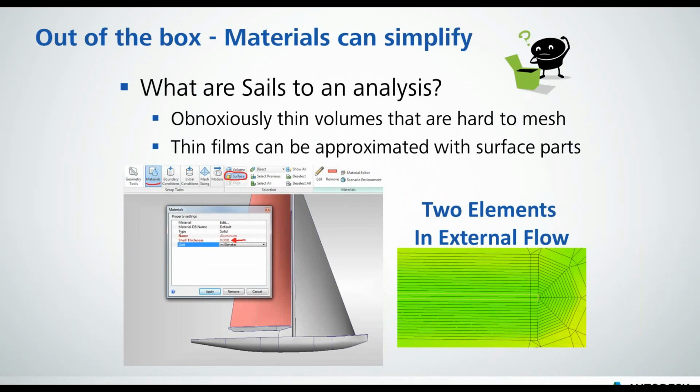We can use our choice of materials to greatly simplify the mesh. If you're working on some kind of analysis that has a very detailed filter, well, we have a material device that will mimic that filter without having to have any of the details of the filter. You can learn an awful lot about your analysis by using those simplifying material devices.